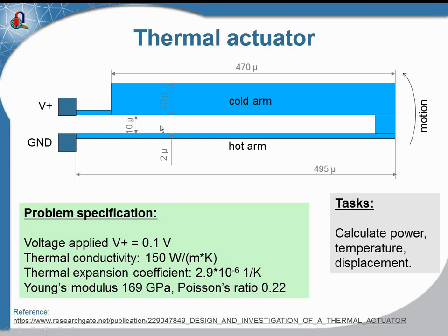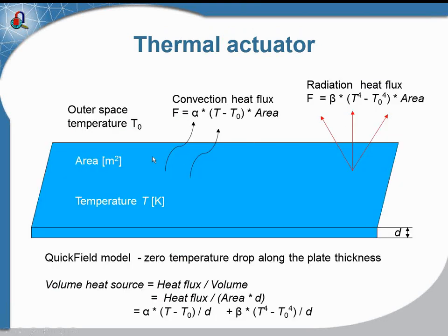The plate is cooled not only from this edge but also from the top surface and bottom surface. Here is the small portion of the plate. Again, we have specified the boundary conditions, and the cooling only from the side surface is very small compared to the top surface and bottom surface.